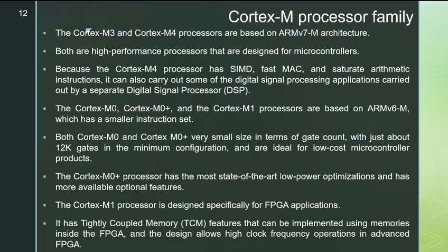The Cortex M1 processor is designed specifically for FPGA applications. It has tightly coupled memory (TCM) features that can be implemented using memories inside the FPGA, and the design allows high clock frequency operations in advanced FPGA.